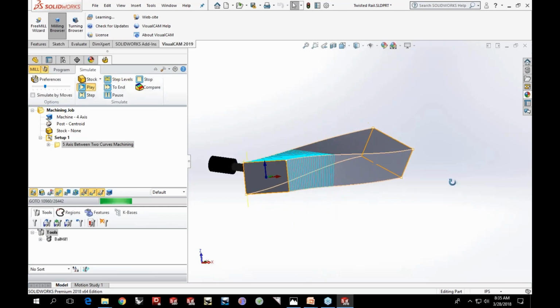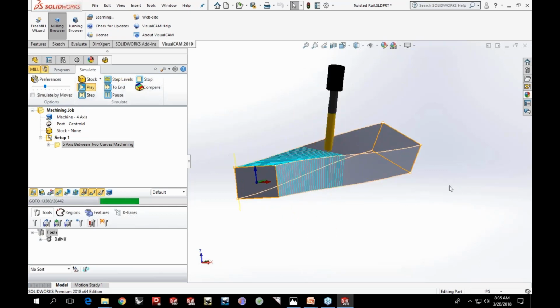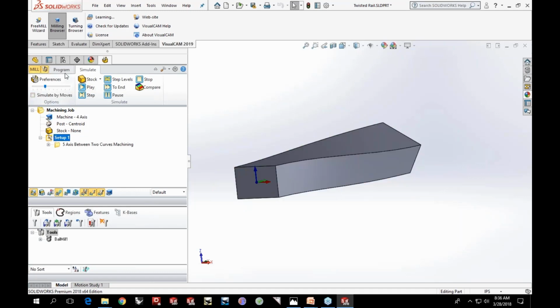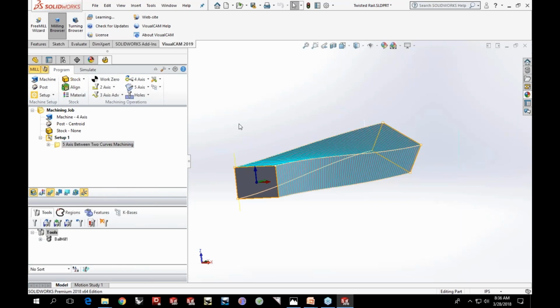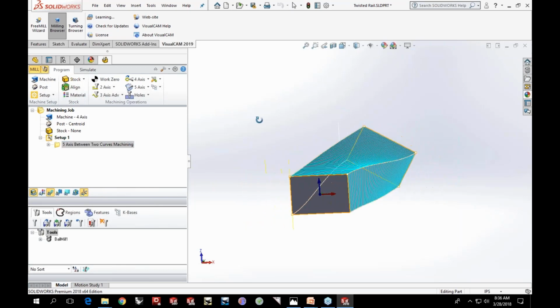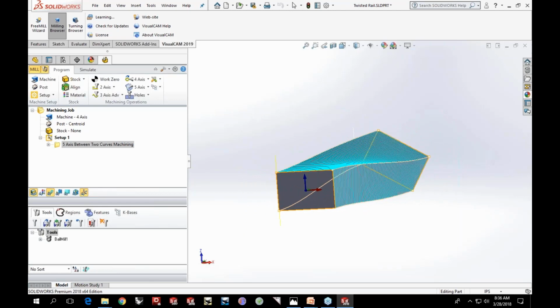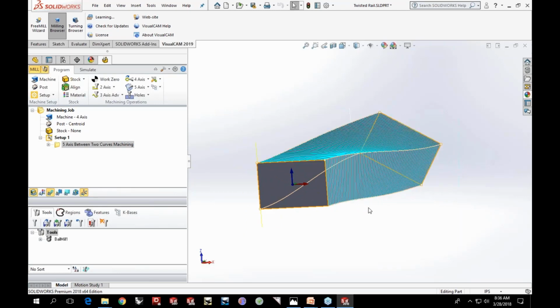Yeah, when Uday says true 4-axis or locking the 4-axis, what he means by that is the tool is constrained to parallel planes that are normal to the rotary axis of the machine. So in a 4-axis machine, obviously you can only change the tool axis in a plane that is normal to your rotary axis of the machine. But in our traditional wrap methods, we keep the tool axis normal to the rotary axis. But what we do in these kind of methods where you have some parts like twisted rails, we need to actually vary the normals along the surface normal. And that's what we do.